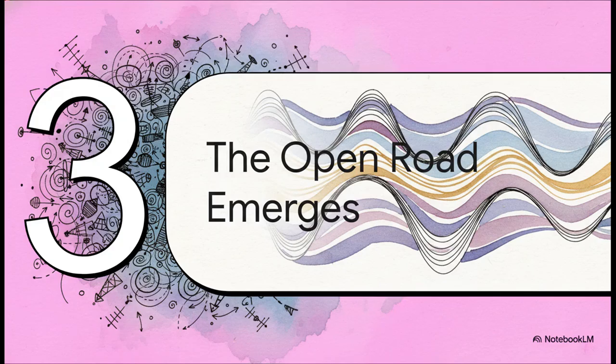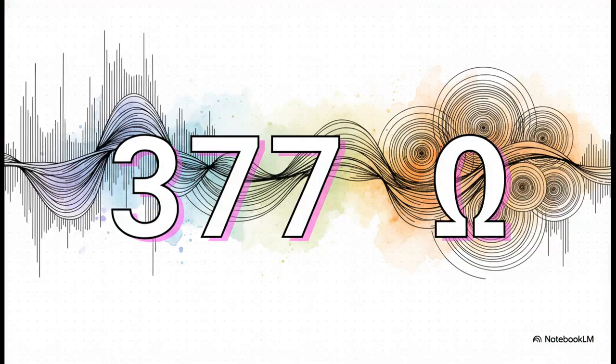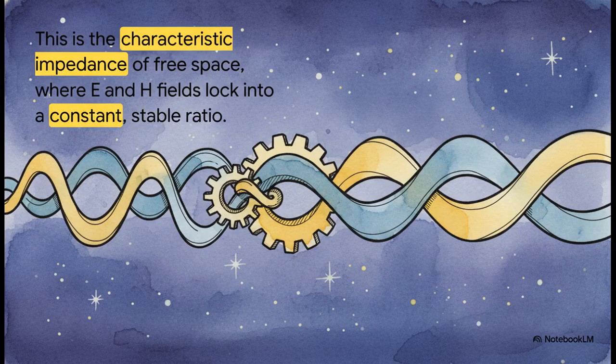But here's the thing. This chaotic mess right next to the antenna doesn't go on forever. As we move away, we get to the far field, and that's where a stable, predictable wave finally emerges. As you travel away from that antenna, the chaos just fades, and something pretty remarkable happens. That impedance, which was bouncing all over the place, super high for an E field source, super low for an H field source, starts to stabilize and settle on this one single constant number. And that number is 377 ohms.